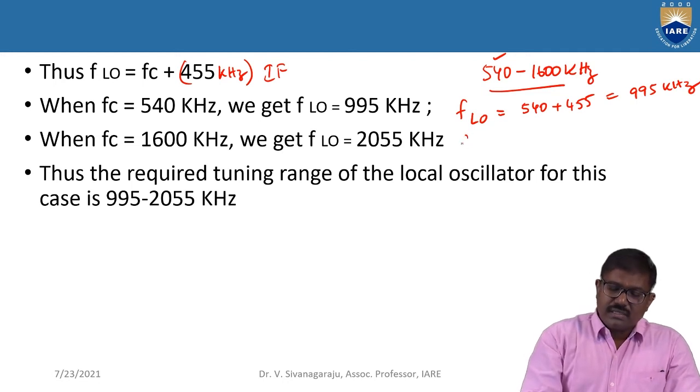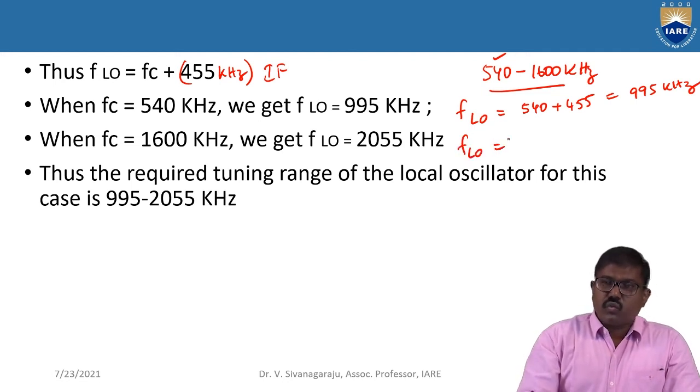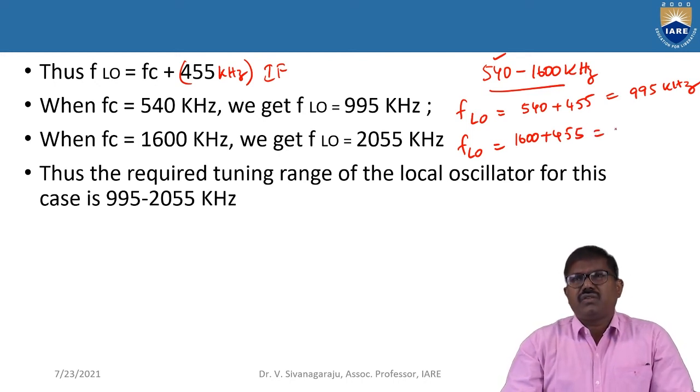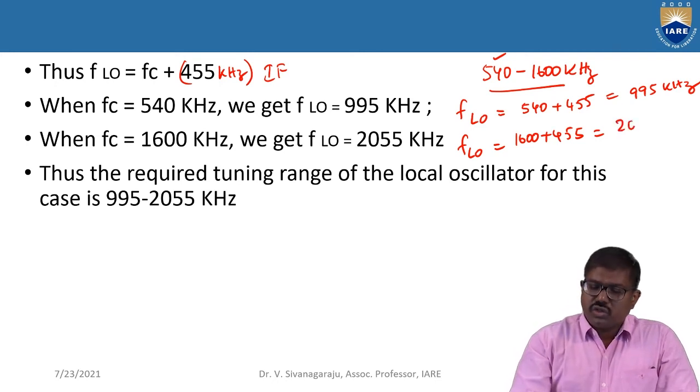So in this case, this FLO is equal to 1600 plus 455, which gives 2055 kilohertz.